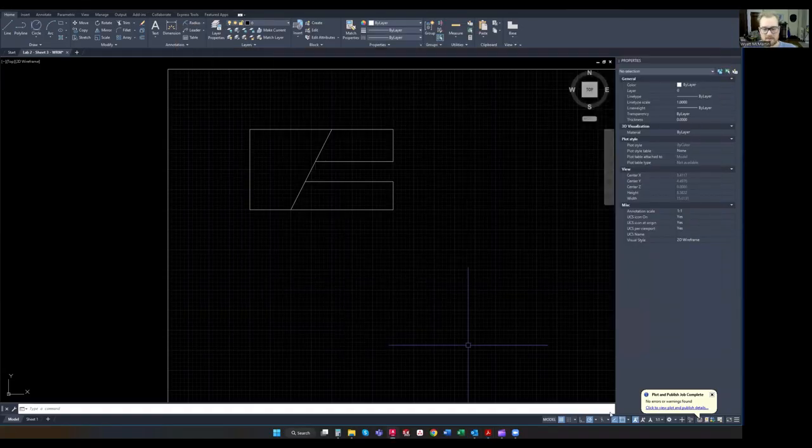So I'm going to turn on my grid snap, grab my line tool, and then starting maybe, let's see. So we have dimensions that are going to come down here and then come up. So let's start 1.5 inches below at that left corner. Start here. We are going to draw a 2-inch line, and we can actually turn off our grid snap now.